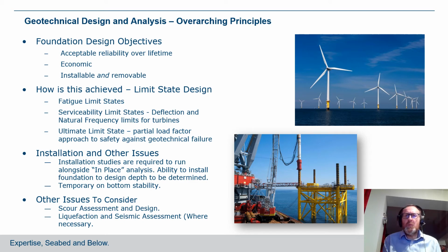As well as the limit state design, we also have to look at the important issue of installation. So we carry out specific installation studies to check that the required foundation dimensions can be installed to the required depths or the sizes that can be produced, and that the equipment that needs to be used to install those foundations will be stable during the installation process. In addition to that, there are specific other issues that we have to look at. Scour assessment, scouring around foundations and the possible impact that might have needs to be looked at. And also in seismic areas, liquefaction or seismic loading also have to be looked at.